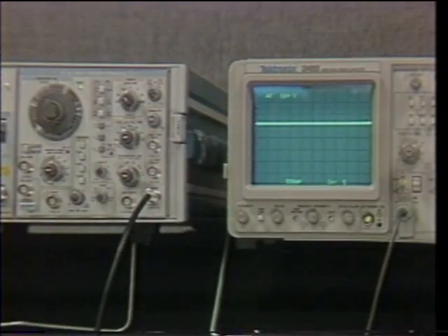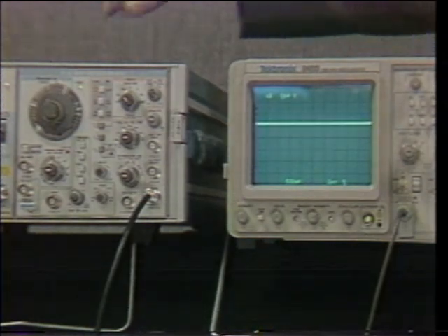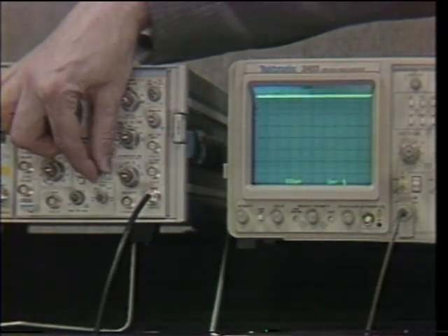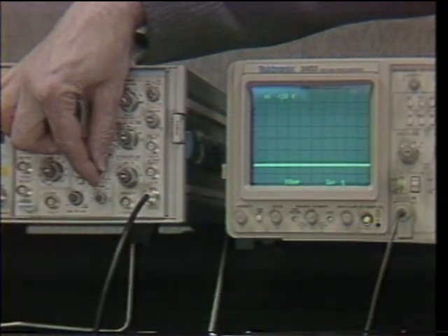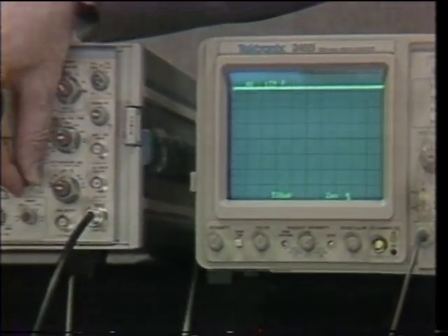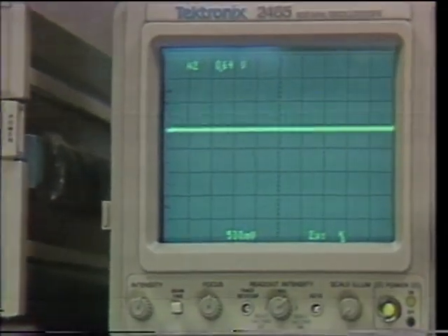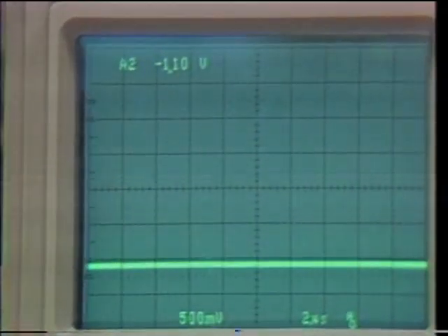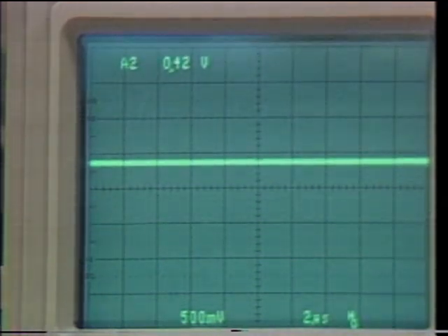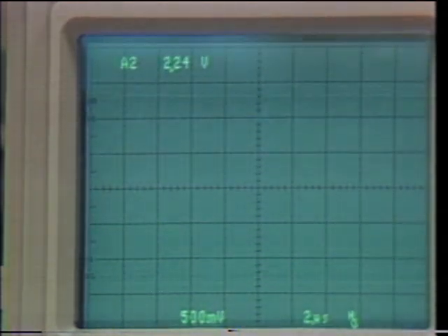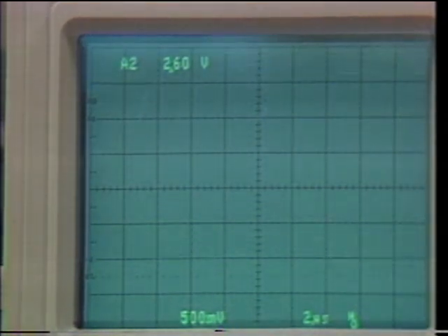One more convenient feature of the trigger can be illustrated with this DC offset control on the signal generator. You can see that as we move this DC voltage to various levels, we have a readout in the trigger level readout that shows us that DC voltage. Now this is convenient for tracing power supply distribution in a complicated system. The accuracy is about 5%.